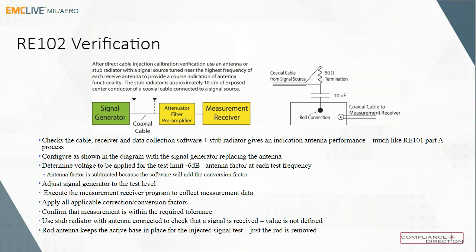Remember that antenna has got a high impedance input circuit, the rod terminates, and it's real sensitive to ESD. So make sure you use a lot of ESD precautions when you're taking the rod antenna away and putting it back in. Get yourself attached to the base of the antenna so you've discharged yourself before you touch that rod connector place. You'll destroy your FET transistors in the antenna.